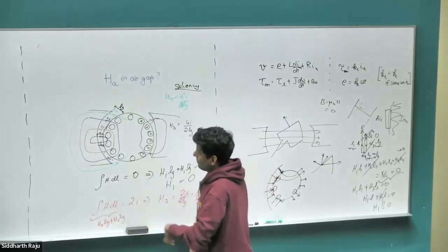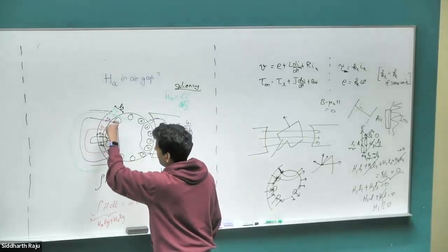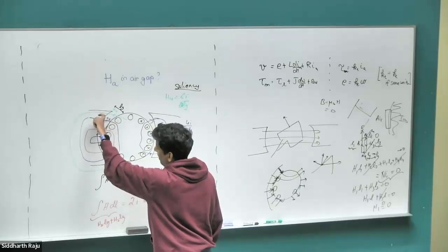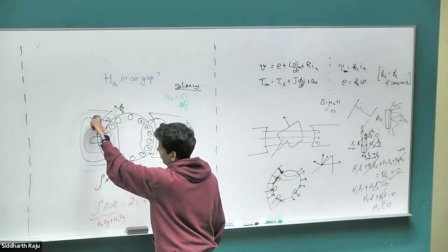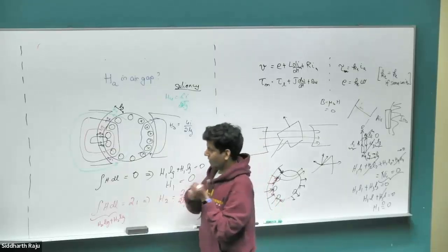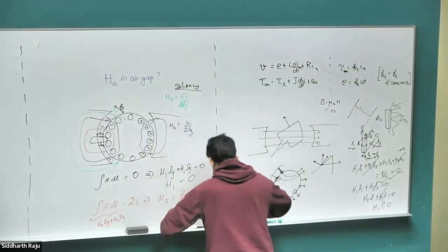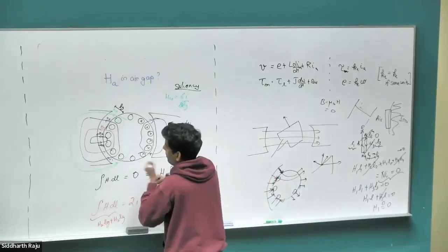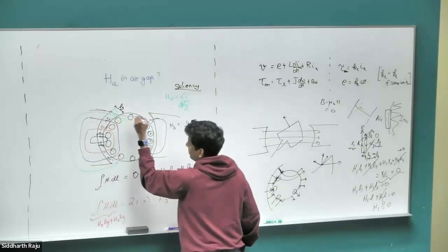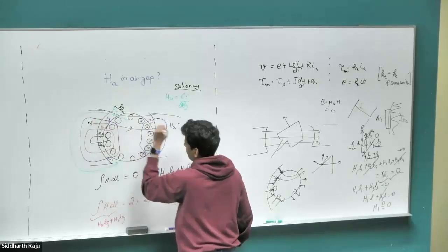So due to the magnetic field of the conductors, we have H fields going on one side of the pole that add to the magnetic field. On the other side of the pole, it's subtracting away from the external magnetic field. So we have our external magnetic field here. Our magnetic field due to our rotor magnets is going in this direction, from north to south.